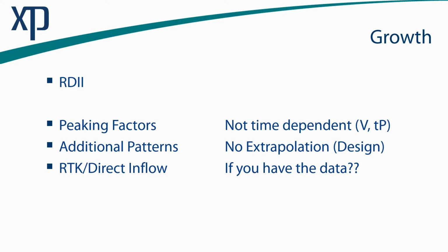But the issue when we have peaking factors is that it does not necessarily help us with understanding the volume of when the flow occurs, or particularly the time to the peak. It's almost like a stormwater person saying time of concentration, but the time to peak on a daily basis for a sanitary system is very important. You may or may not have additional patterns of information to try and plan for certain circumstances. This is typically done in a design mode.